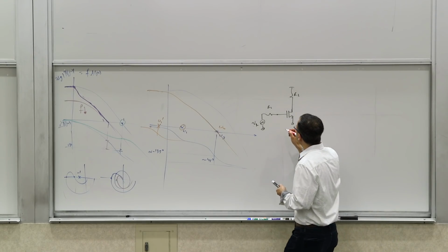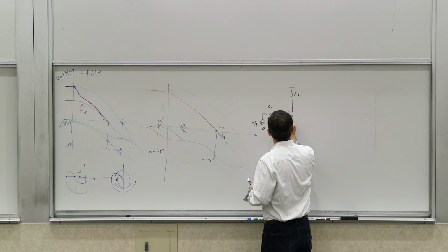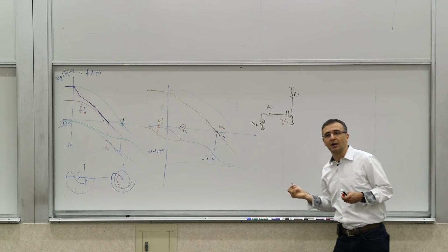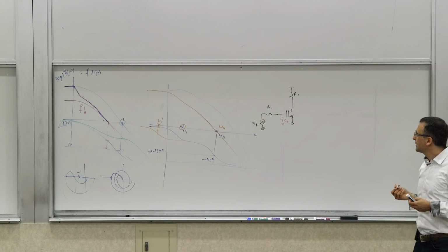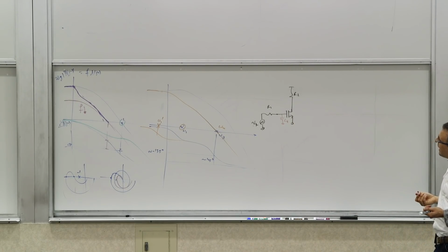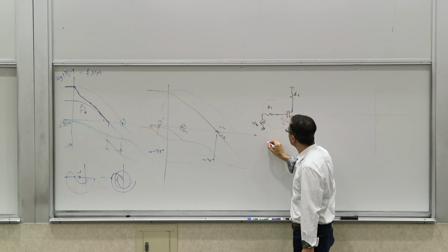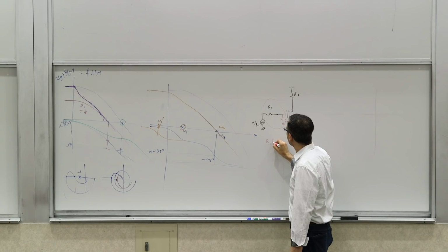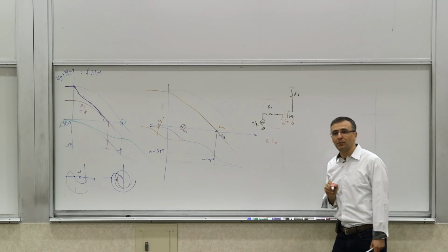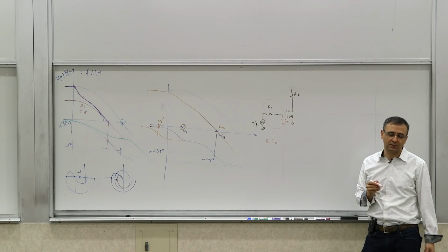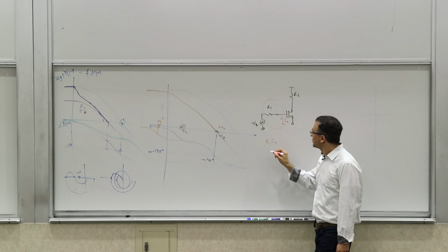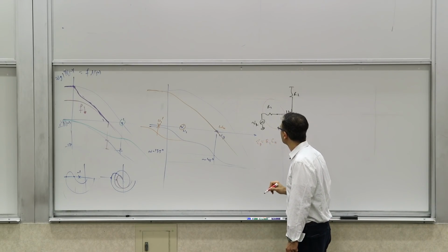Well, one of the ways to do it is, imagine you have what we call C-pi, CGS, C-pi, in a transistor. So what can we do when we have a pole at the input? In this simplified version, we have an uncoupled time constant. If there are no other capacitors, it would be the only time constant, so it would be tau pi, right?